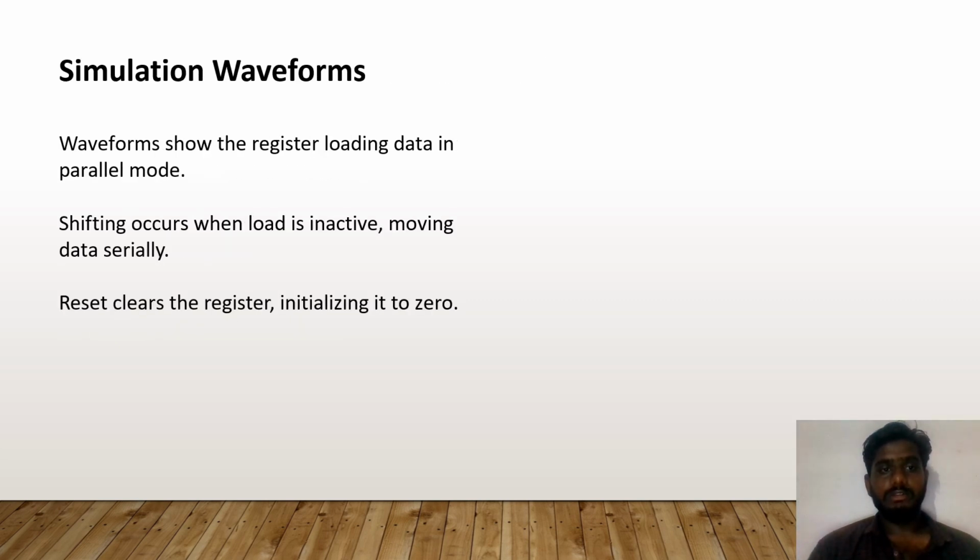Simulation waveforms. The waveform shows the register loading data in parallel mode. Shifting occurs when load is inactive, moving data serially. Reset clears the register, initializing it to 0.